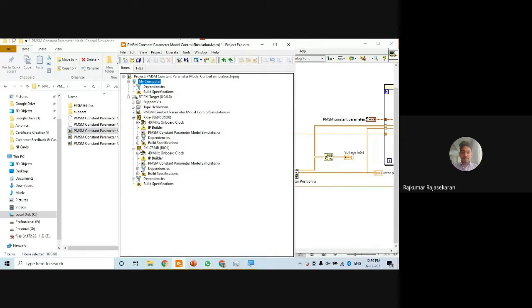So if you see, there are two motor models available. Different cards will be available inside which contain FPGA. This hardware is called PXI hardware, NI PXI, which is mostly used for HIL or for test and instrument operation, for high channel count or with tight synchronization options. It's basically a computer meant for test, control, and instrumentation. Nowadays, it's used for HIL option as well.